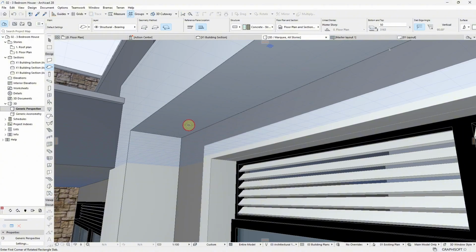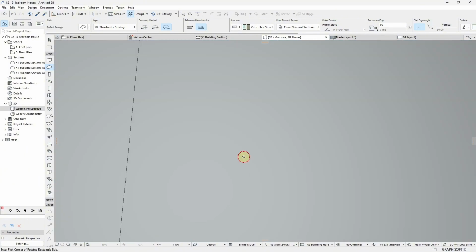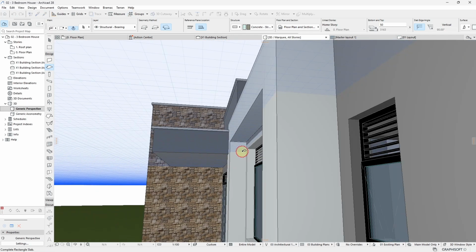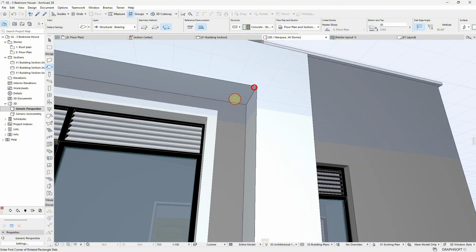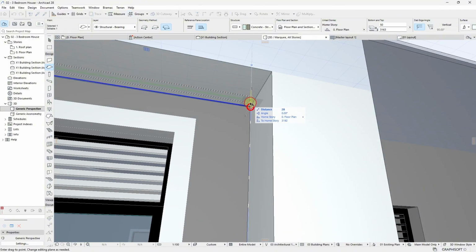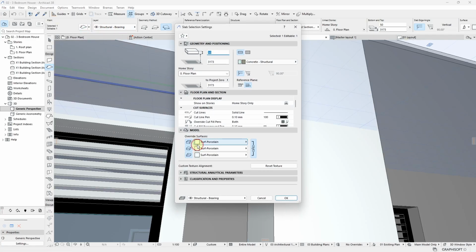Now, underneath this part up here, I'm going to put a strip light to go around. So I'm going to bring this back by 10 millimeters. Then I'm going to come here and I draw a slab of 10. I come and I attach it at this point. I select it and I move it up a little bit by also 10 millimeters. And then I change the texture or the color to a different color that I'm going to assign a lighting material to, maybe something like this.